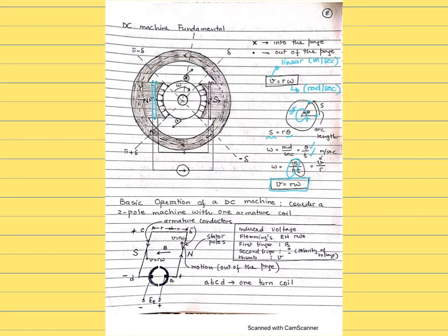And it's connected in here to the other side pole. So that means it's connected in series. Okay. And the direction of the current is given by this source in here. So that's the direction of the current. It's going to come from the bottom and come up, then down in here. So that is where it flows, comes up from the bottom and comes down from the top, and there it is. So that's the direction of the current flowing through the field winding.